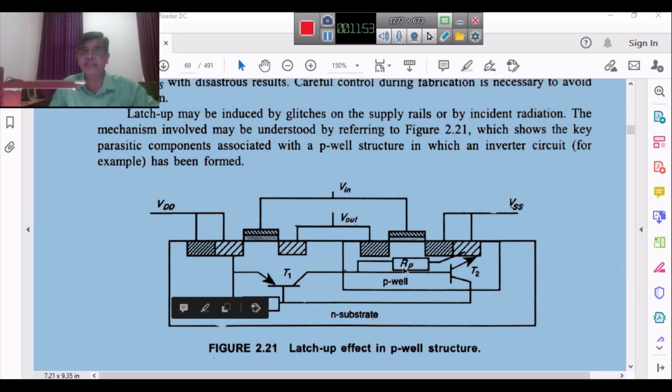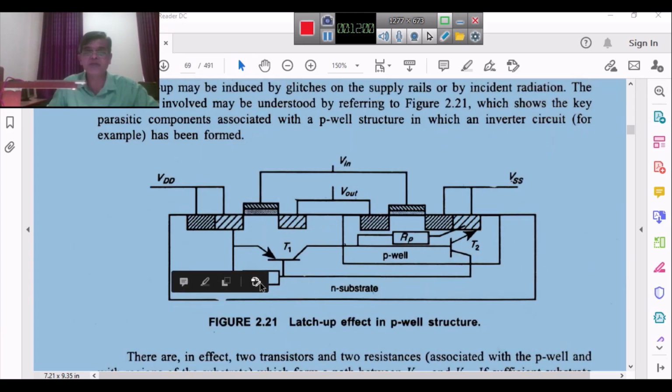It is the well resistance. Similarly, there is substrate resistance. Your substrate resistance is something like this. You can see this is RS, correct? Substrate resistance RS comes between this point. What is this? I said P type, between this P type and your base, this is P type and this is N type. So the substrate resistance appears here. Okay, so I get some resistance connected here.